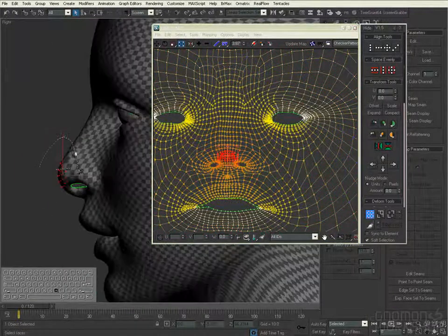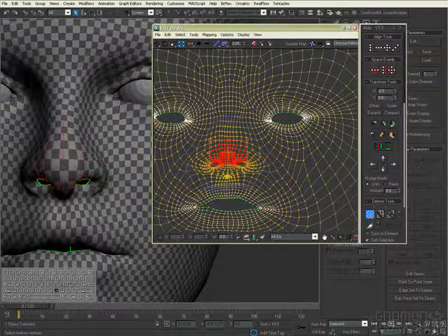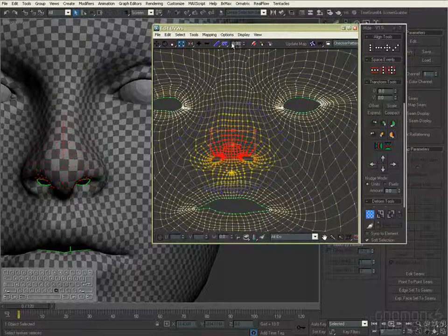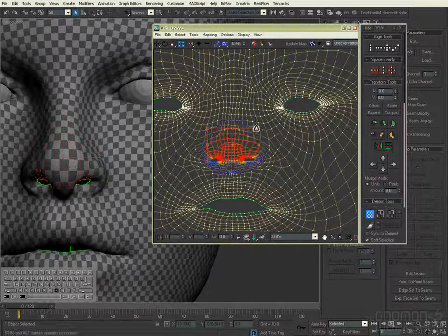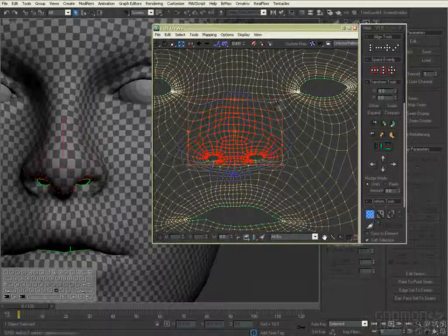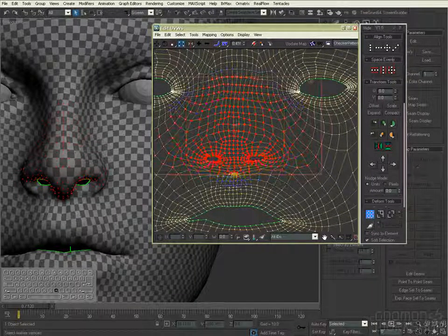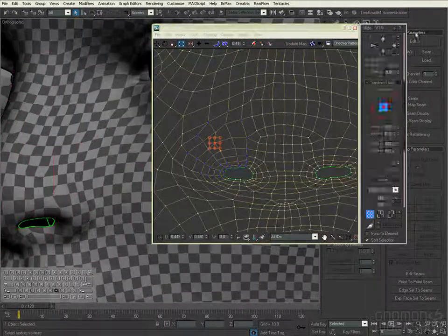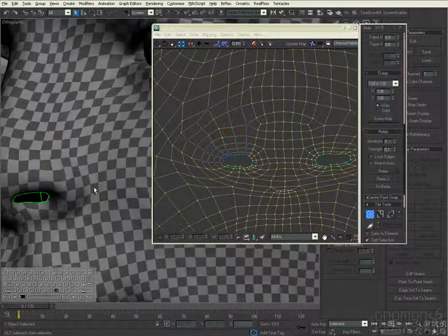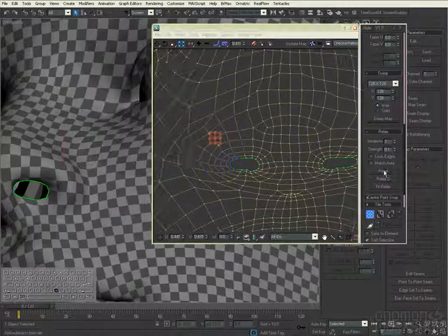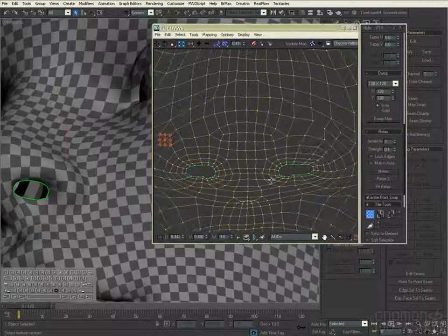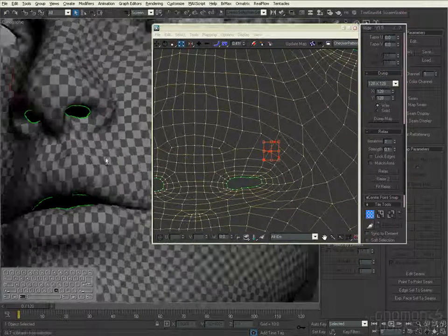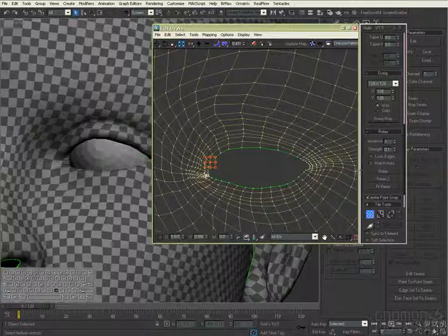So instead of making a huge map, I would recommend scaling the face up a little bit. It will be distorted on the boundary where the face and the hair cap meet. But since we're using texture projection in ZBrush and BodyPaint, we don't really have to worry as much as before. Before BodyPaint and ZBrush, I used cylindrical mapping that gives you very little distortion, but there will be a lot of stretching on the top of the head.